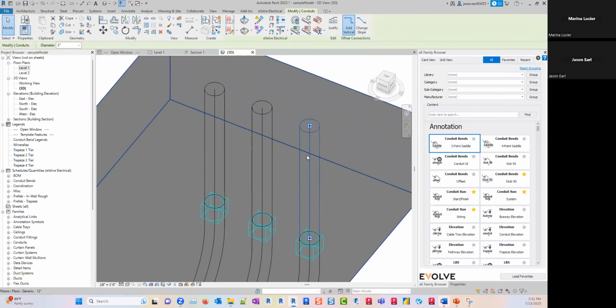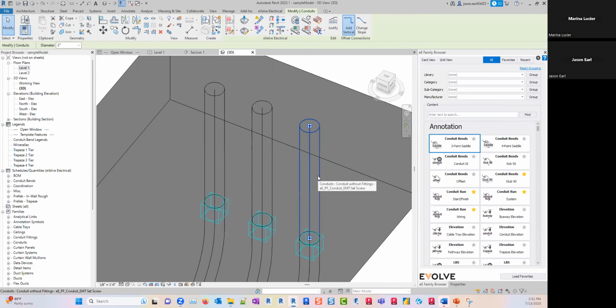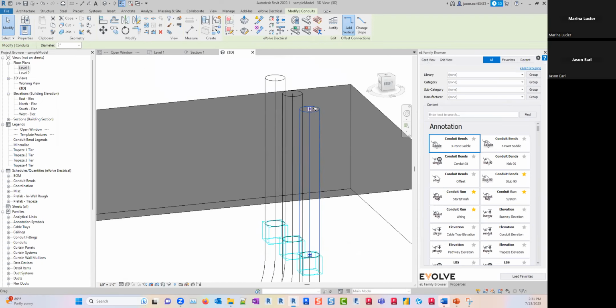And I've got those connectors, that's great. But what I'm interested in, what the question that I need to ask Revit with my Dynamo script is, which end is not connected to anything? Because remember, really, I want my point up here. I don't really want my point down here. And I certainly don't want 2 points.